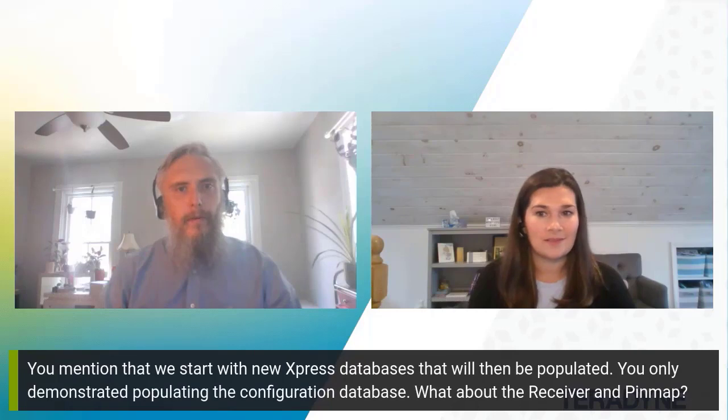So as we wait for some questions to come in, I have a question to get us started, something that I know I've heard asked before. You mentioned that we start with new Express databases before creating a test in the digital test editor that will be populated, and you demonstrated populating the configuration database. What about the receiver and the pin map? Yeah, of course. The receiver and pin map databases will be populated by the digital test editor when the DTB is imported.